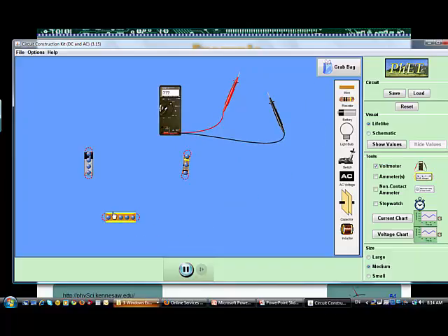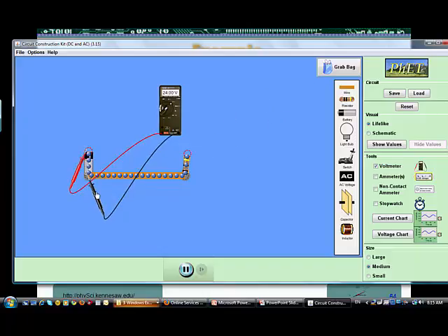So now I'm going to take a wire and connect the battery to the resistor. Now I'm going to do the same thing to illustrate a point. Okay, so the voltmeter is here. Now I go to the negative of the battery. I still read the 24 volts. Now as I move this around the wire, I should have the same electrical potential here. So I should continue reading the 24 volts. Now since I don't have a current through the resistor, there is no voltage drop. So I still read 24 volts.